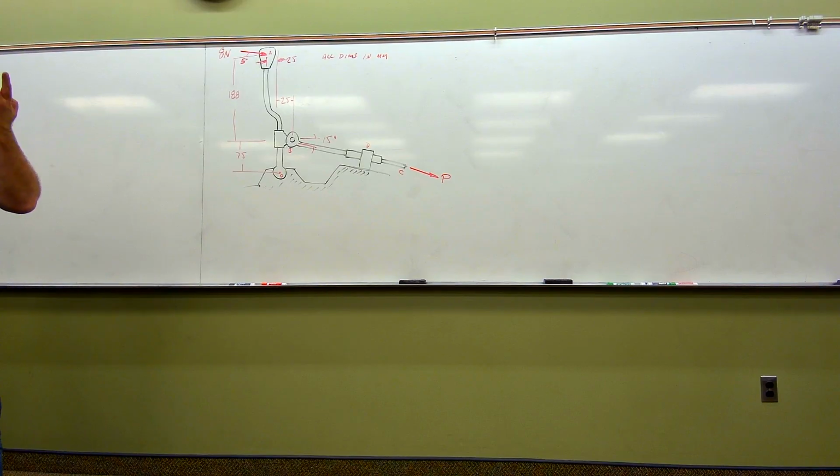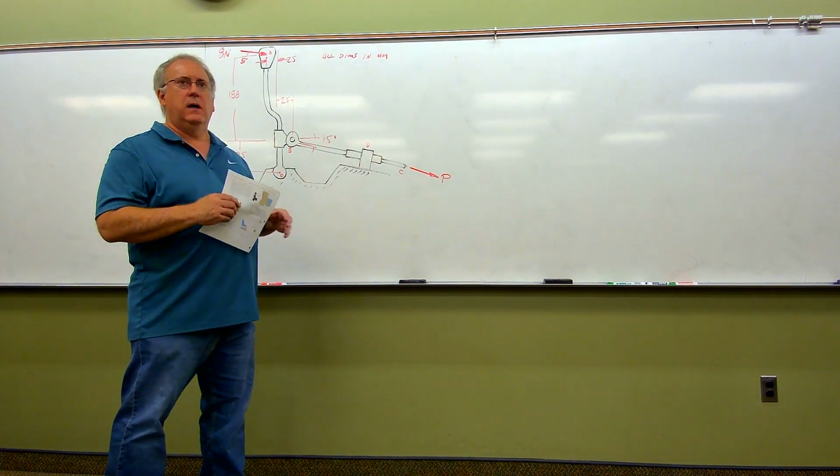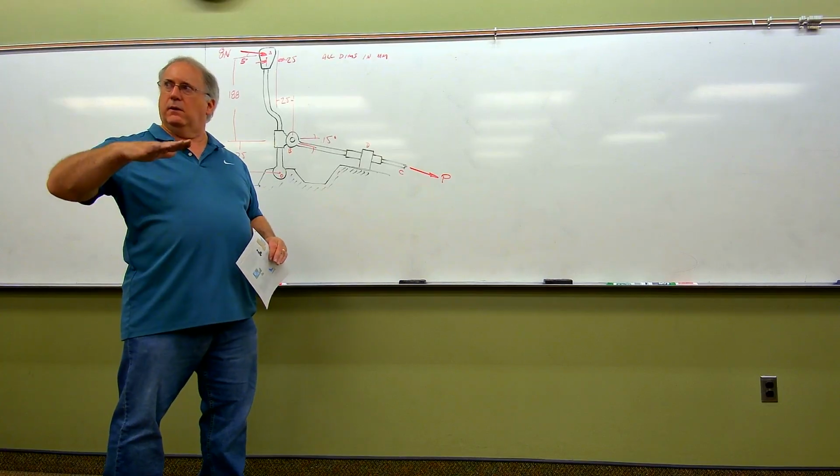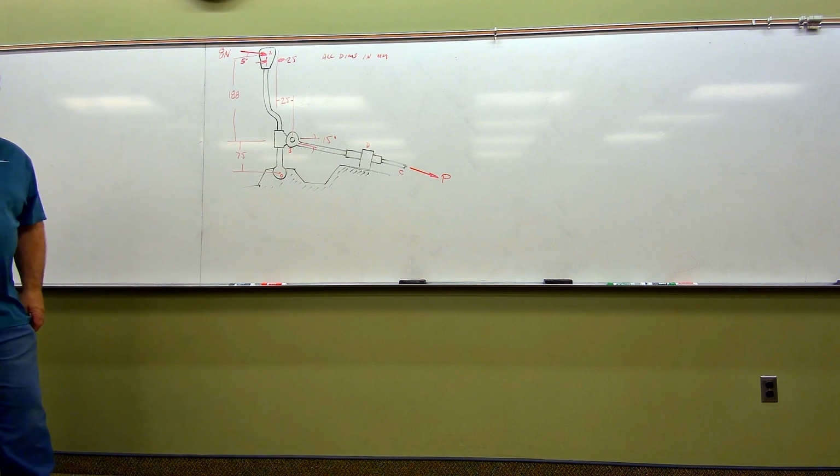And then one last thing. Note that a soft rubber bushing at D allows the slip tube to self-align with link BC. That's what's being shown right here, folks. There's kind of a soft surface in there, which accounts for a little bit of motion as we operate at slightly different angles.